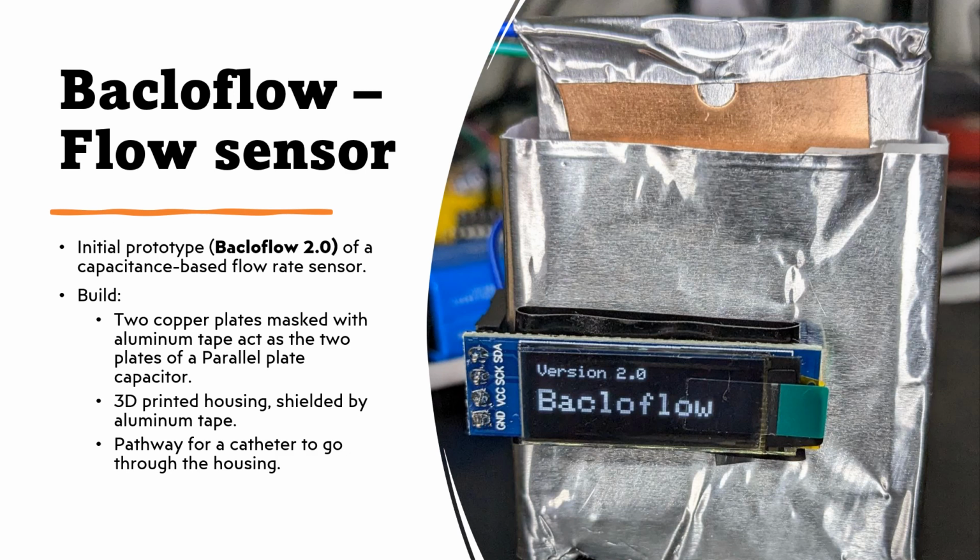It's a capacitor-based flow rate sensor, and the capacitor is made out of two copper plates that are masked with aluminum tape, and the entire device is shielded by aluminum tape so that the capacitance stays stable. As you'll see when I'm demonstrating it, there are a lot of stability issues with the capacitance. It really is affected by environmental changes and conditions.